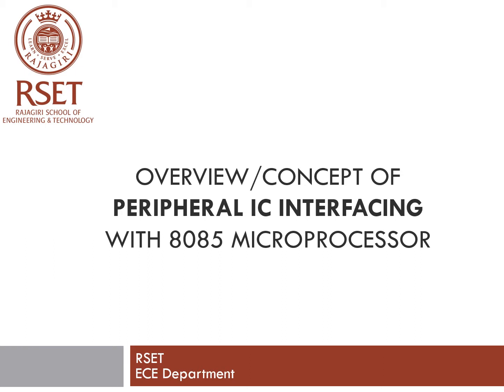Here, we plan to use programmable peripheral interface chips which are designed to work with the 8085 and other microprocessors so that we have a flexible design which can be used for different microprocessor based products. These designs help reduce the work done by the microprocessor in order to talk to an I/O device.